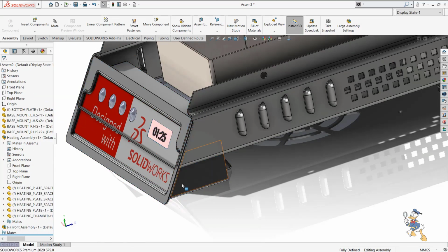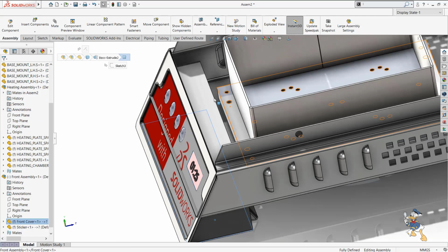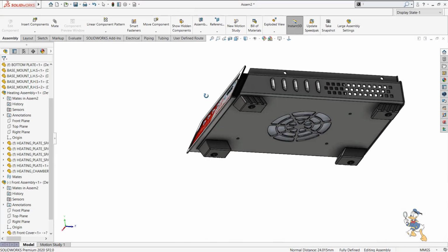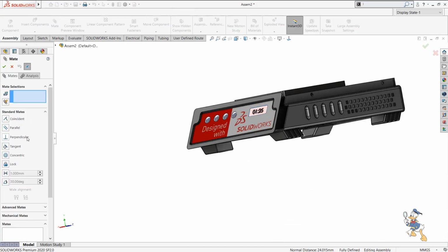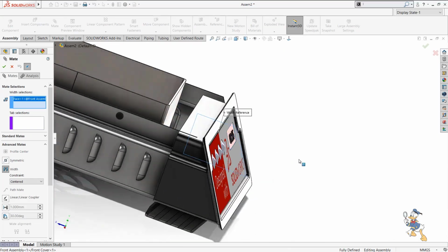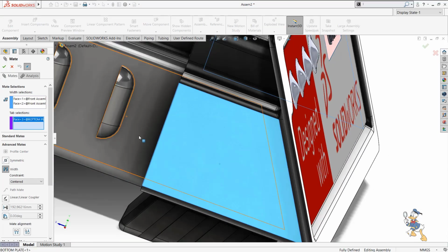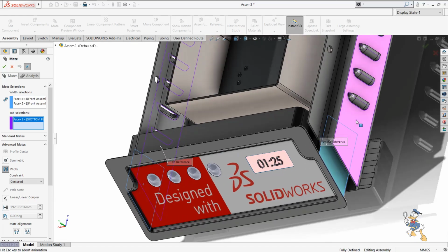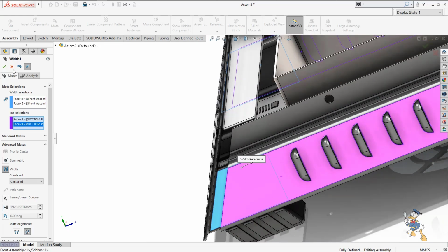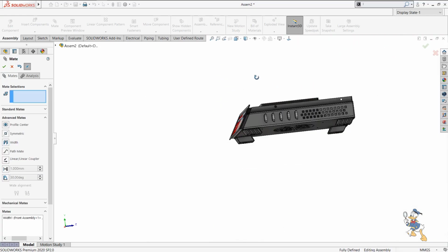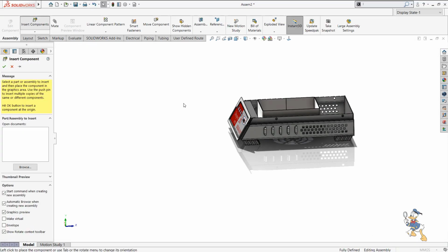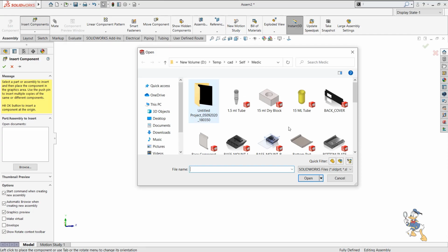So by making it float, I need to provide a coincident mate to this, and now I need to make some sort of width mate with respect to this face, this face, this face, and this face. And yeah, this is concentric. Oh, sorry, width mate with each other. Suppose I just need to cover up this assembly with lid 1, so I just need to select the lid